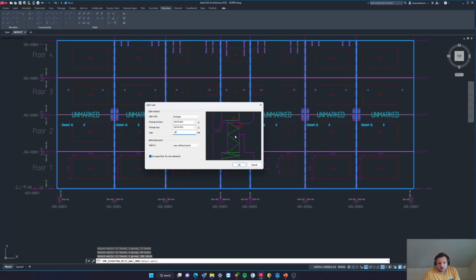So you need to be a little bit careful, but I will do it in this case. And then you can decide how you want to split it. We have the options to do it like a maximum wall height, or to create one wall, where you just put the height of the first wall and then we do one split. You can use your floors, or as we're going to do, we're going to pick points.